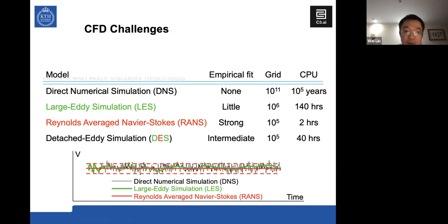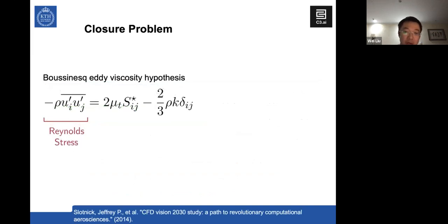But the RANS equations are still highly nonlinear, and they introduce the so-called closure problem. The closure problem is often handled by modeling the Reynolds stress using the Boussinesq eddy viscosity hypothesis, which establishes a linear relationship between the Reynolds stress and the mean strain rate. The eddy viscosity hypothesis is renowned to be physically wrong, but nevertheless used. Such an assumption further increases the uncertainty of the numerical simulation, which is another reason that none of the RANS turbulence models can ever be accurate for all ranges of flows. And these are the main of numerous uncertainties raised by CFD.